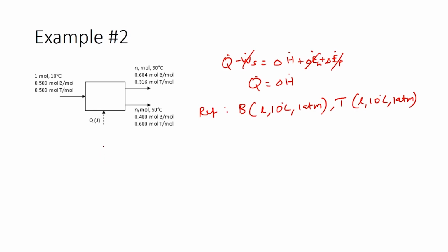The enthalpy table would have all the substances, which would be benzene liquid, benzene vapor, toluene liquid and toluene vapor. Here you also have the flow rates which you have to write down: N dot in, enthalpies H cap in, N dot out for the outlet flow rates and H cap out for the specific enthalpies of the outlet streams.